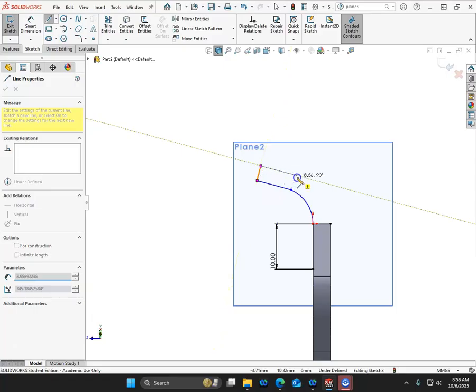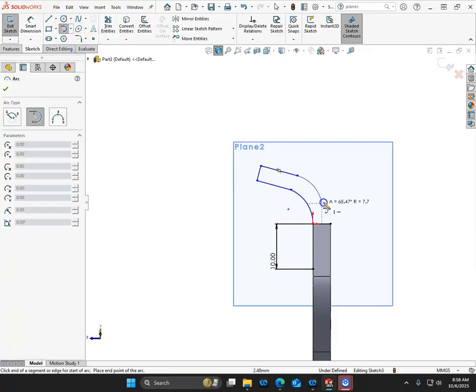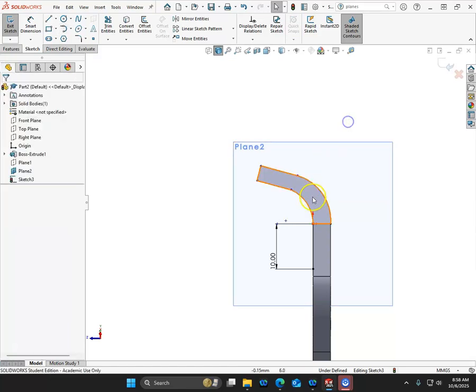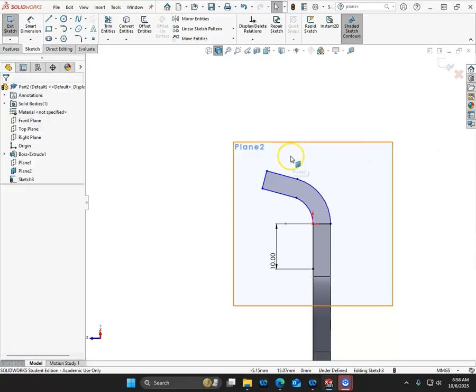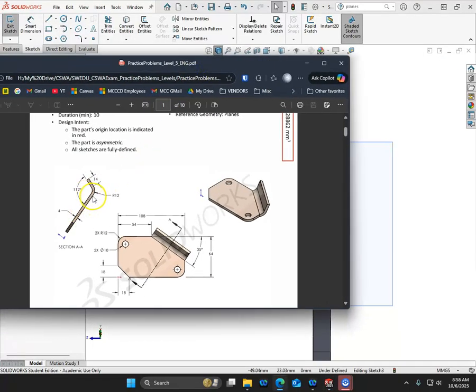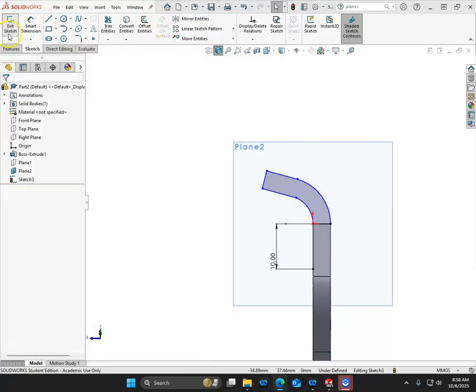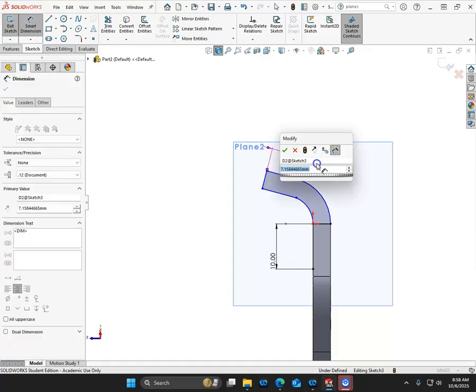I could also do the offset. Wanted to make sure that the tangent arc is also going to the base. Now those should be concentric. So we're looking to make those concentric. Our overall height, let's go ahead and pull this in. We have 112, a radius of 12 on the bottom side, so that would be radius of 8 interior and 14 on the back edge. So smart dimension, make sure that we're staying in the linear.